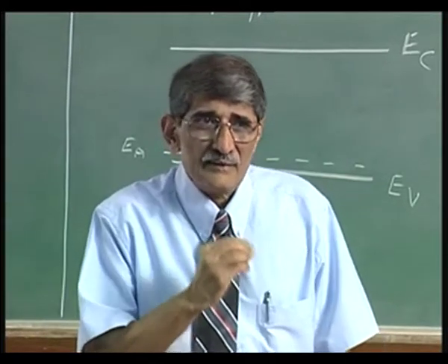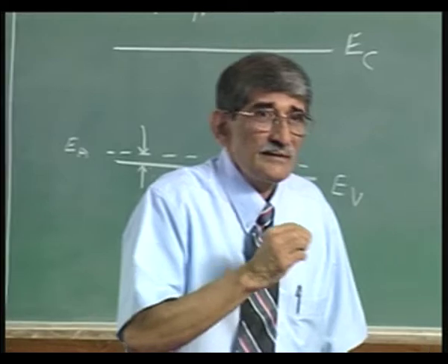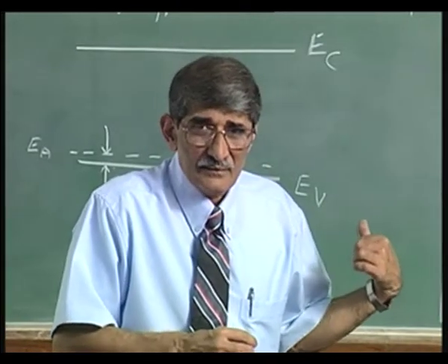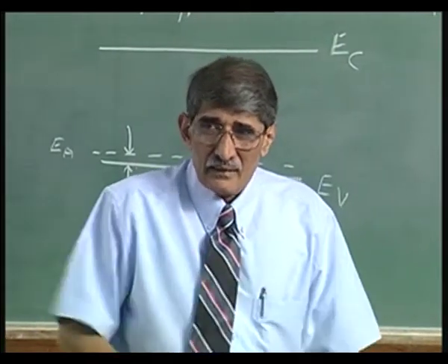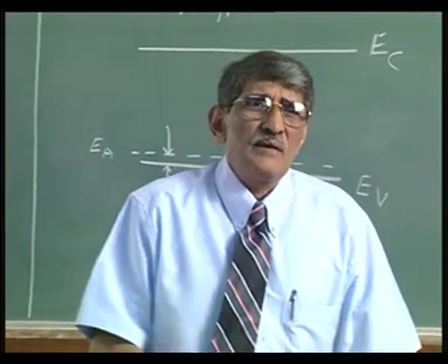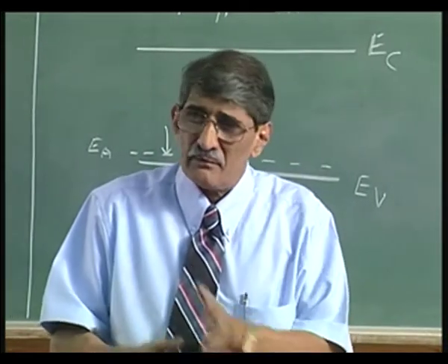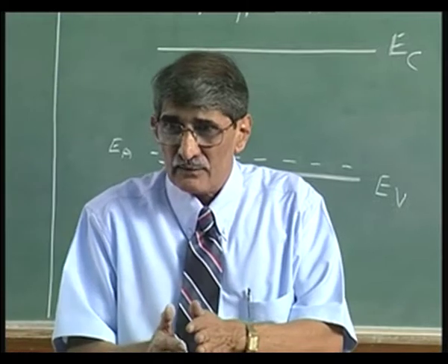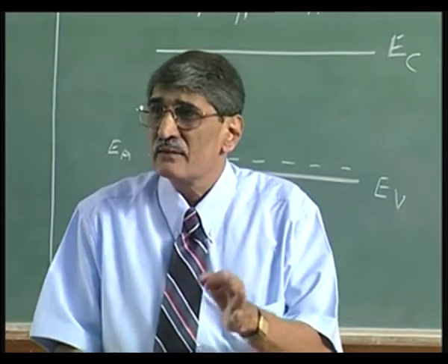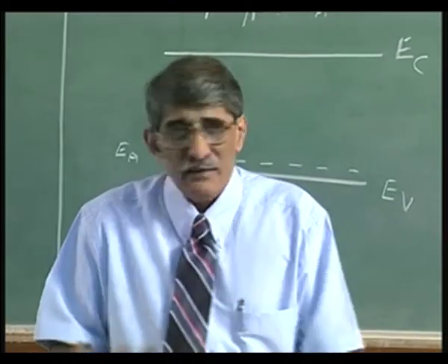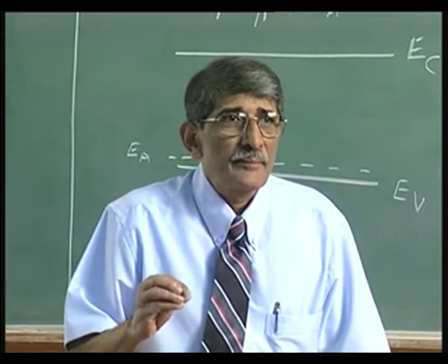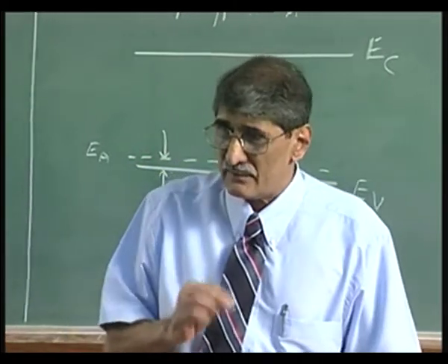So, this is one of the advantages. You are cutting down lattice scattering by going to lower temperature. Okay. Now, of course, you will be worrying, what about ionized impurity scattering? We have got methods of separating the donor and acceptor to prevent the ionized impurity scattering. That we will discuss when we go to high electron mobility transistor discussion.